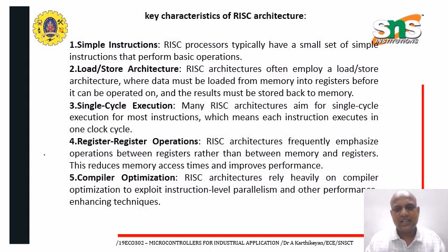The main characteristics of the RISC architecture are simple instructions, a load/store architecture, single cycle execution, register operations, and compiler optimization. These are the main key characteristics of the RISC architecture. The simple instruction set has a small set of simple instructions to execute and perform operations. This is the main advantage.